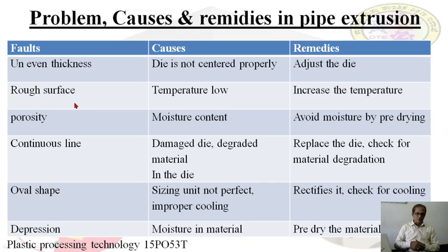The second defect is rough surface. If the temperature is not sufficient, a low temperature is the cause. And how do we overcome this problem, rough surface? We have to increase the temperature a little bit, so that we can overcome this problem.